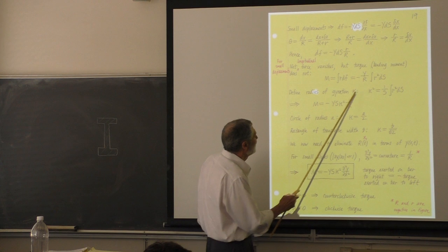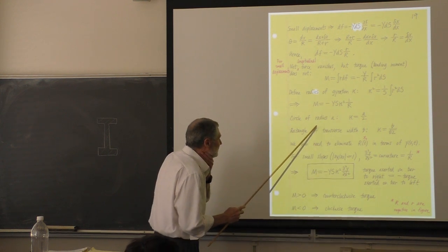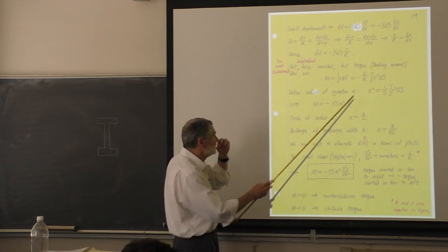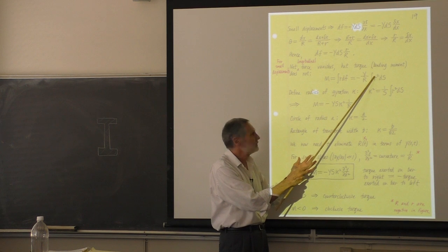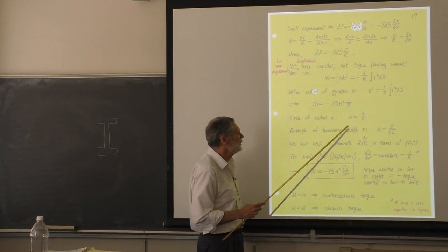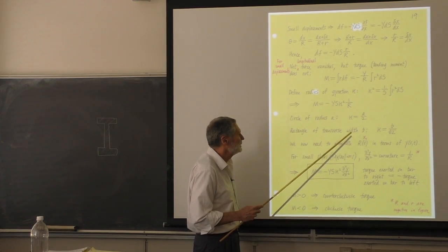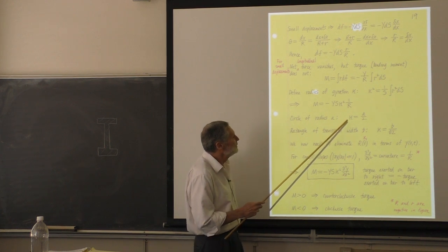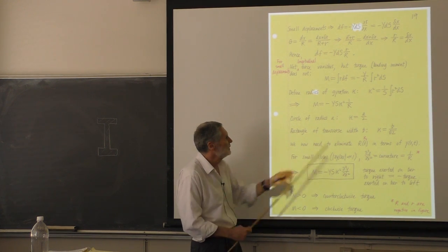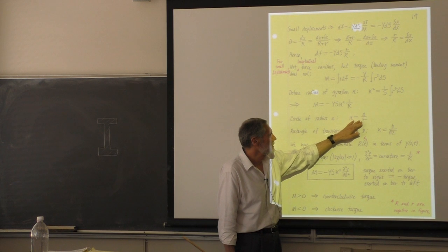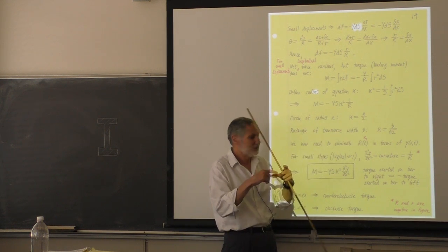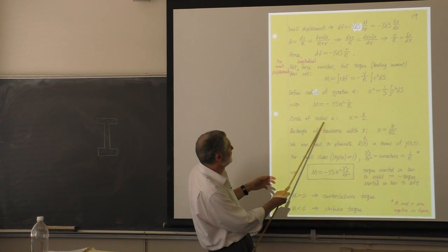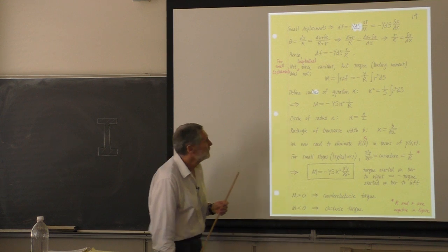The radius of gyration. Now, before we go on, we better talk about different radii of gyration. This is just simple integral calculus, a purely geometrical thing. You can show, and we might show one of these in a problem set, that for a circular cross-section, the radius of gyration is the radius of the circle, that's what this A is here, divided by 2.